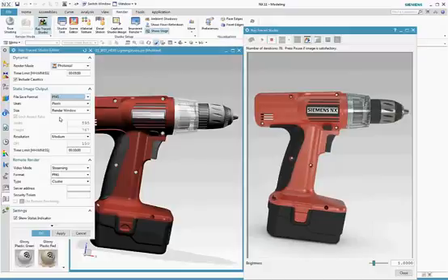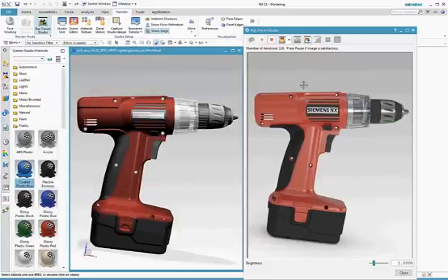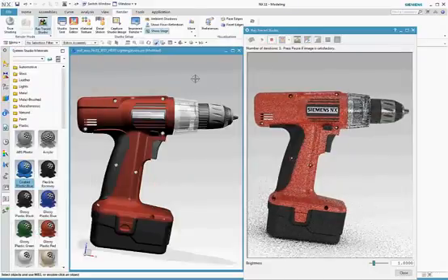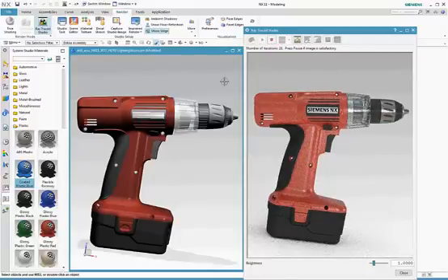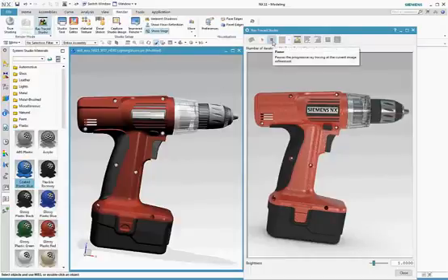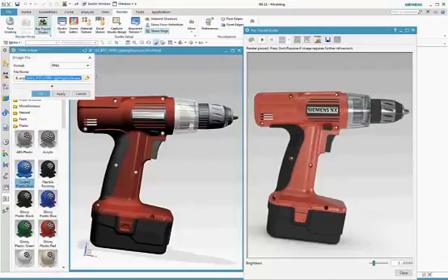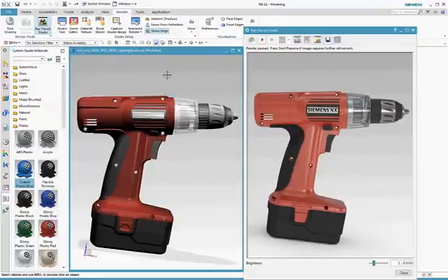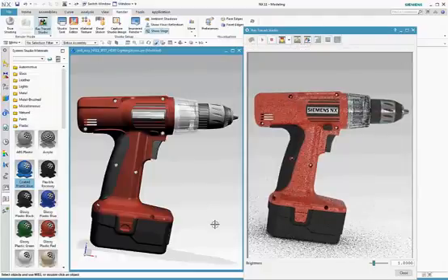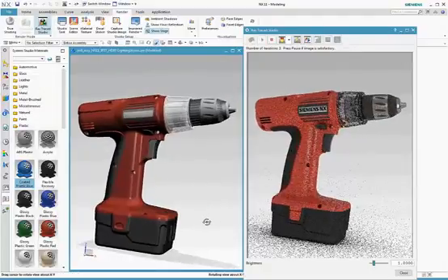For static image setup, you can pick the file format, you can render to window size or bigger than window, and you can set a time limit. Hit the Start Shade button to render your image at the highest quality level. You control the duration by either waiting for the time limit or hitting pause. Save the image to a file, specifying the file path and name, and hit OK to save the file. Hit the Erase button to return to the dynamic progressive rendering.